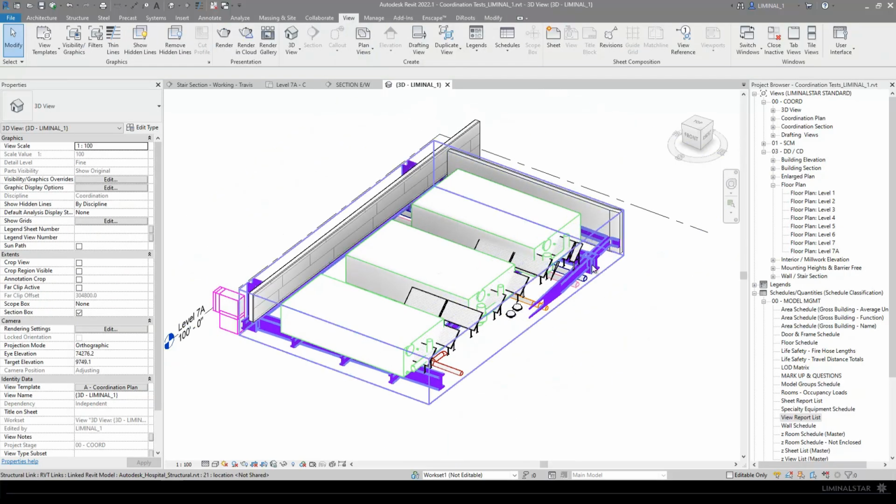So what I would do is rename this view to prefix with the disciplines involved. So maybe it's going to obviously be mechanical underscore architecture, and then I give the view name something like mech equipment versus photovoltaics.